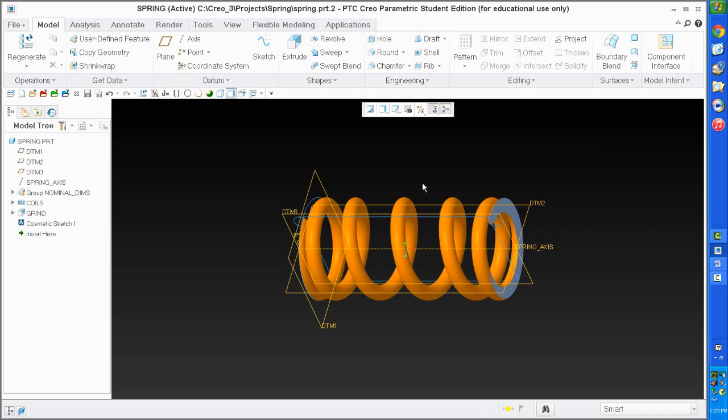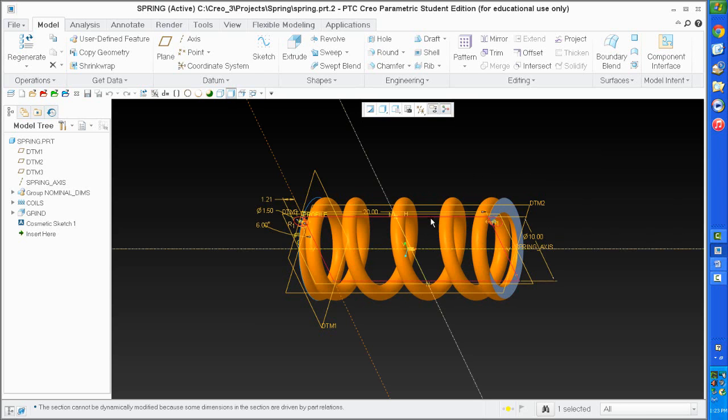Well, I'd have to create a parameter saying we started at 10 mil. What do we got this set? Right now we got it set for 20 millimeters, so our base height is 20 millimeters. So I'll have to create a parameter and set it to 20 millimeters. That way I can compare this number to the base height, find out how much it's compressed, multiply that by the rate, and I can get a force. But if I don't want to create a parameter, I can do it another way. There's a little trick that I use.